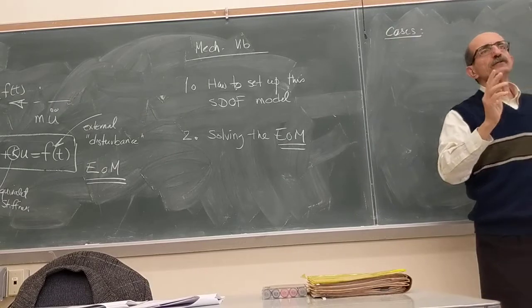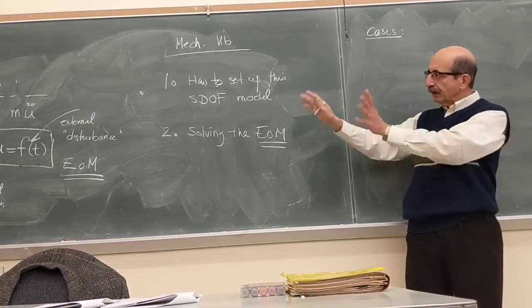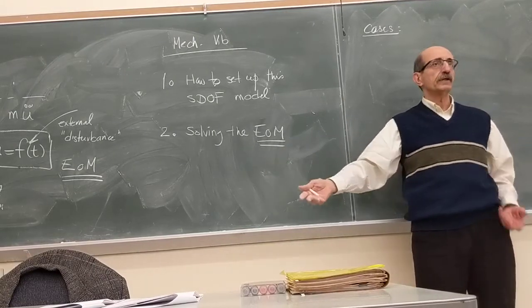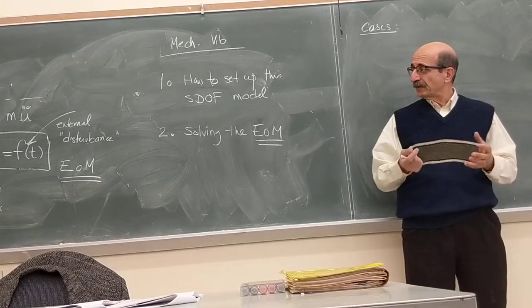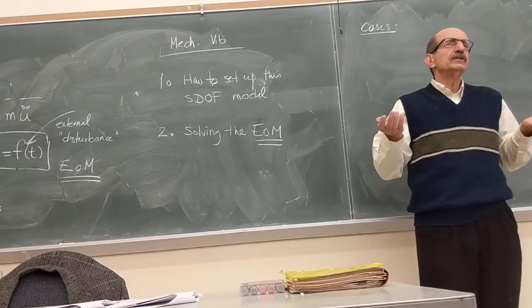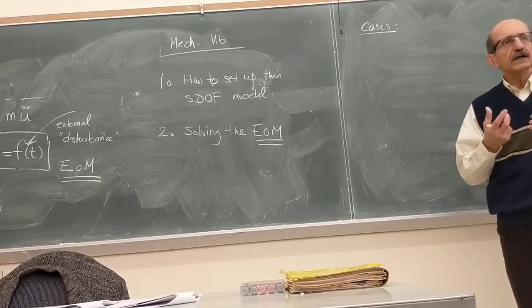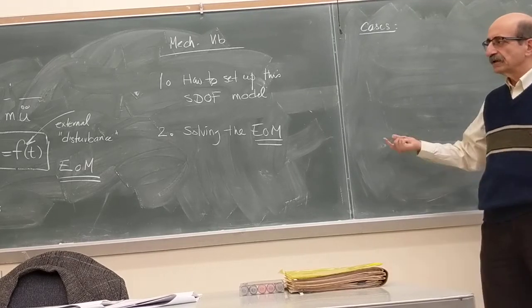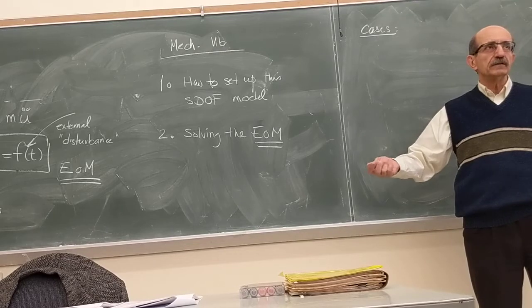First, we make two major assumptions. One is that, in that modeling part, as we set up the equation of motion, as we define the system and so on, the physical system has no energy absorption capability. It only consists of a system that can resist deformation, and that's it. In fact, in strength of materials, that's all you did.